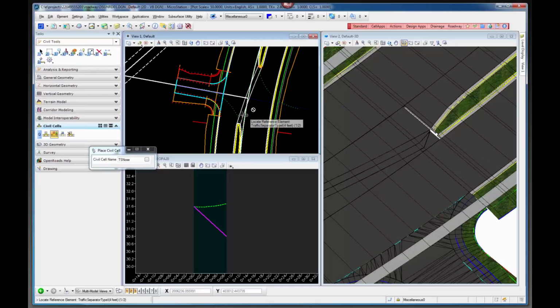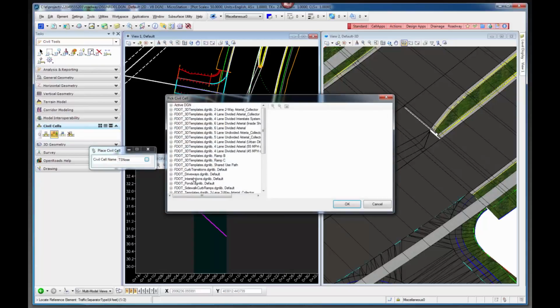But so the first thing, it's actually in the intersections also, and there's a directional median opening, and this is based on the first index detail sheet, and the other two are basically for wider trucks and wider medians, but this one can be adjusted to accommodate for those as well. It's just a matter of changing the dimension offsets. But I'm going to go ahead and place this one just so you know how to place it.